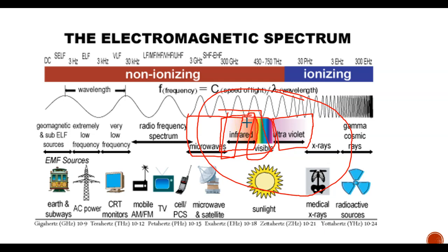And there are some ways to heat the house using infrared and radiation, and this is radiant floor heating. And there are panels that actually radiate heat, and instead of convection, it's not heating the air, it's heating you. The best way to think of those types of heat is when they put the food in the fast food restaurant under a light, that light is actually giving you infrared, so it does heat the food and not the air.